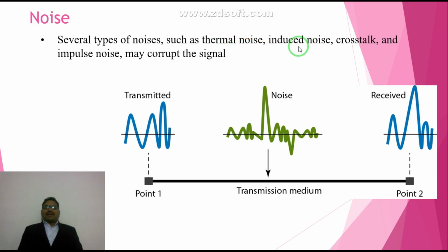Induced noise is induced due to some electrical appliances, such as motors, radios, welding machines, anything which operates on electricity. So what happens is that these appliances, which induce noise, act as a transmitter, and your transmission medium acts as a receiving antenna.